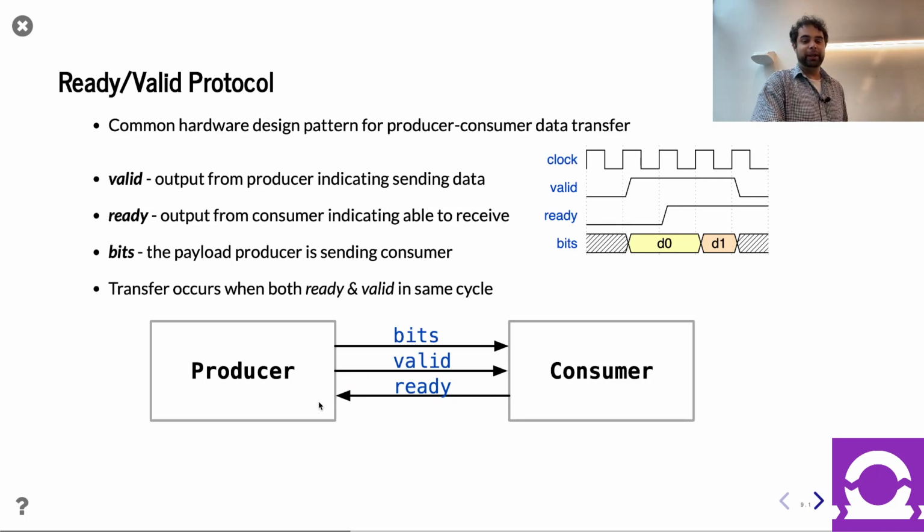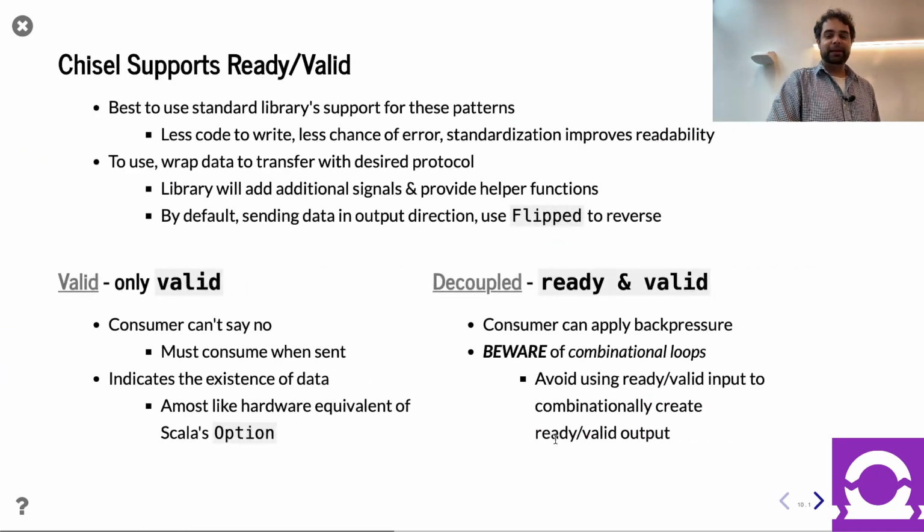But if only one side does it, as soon as the other side does it, the tools will immediately yell at you. It's not quite a case of, oh, there's a combinational loop there, but I didn't find it. No, no, no. At elaboration time, the tools are going to say you made a combinational loop and warn you, right? But like I said, if you can avoid doing this, your module is more reusable, because that way the other side, if they want to make the combinational loop, they can, but it won't be your fault, it'll be their fault.